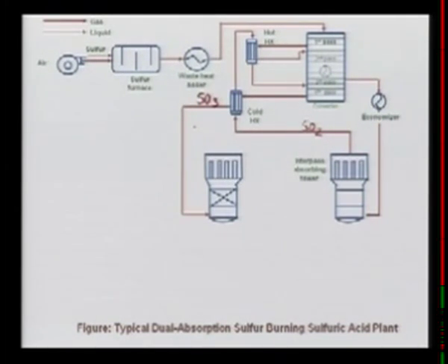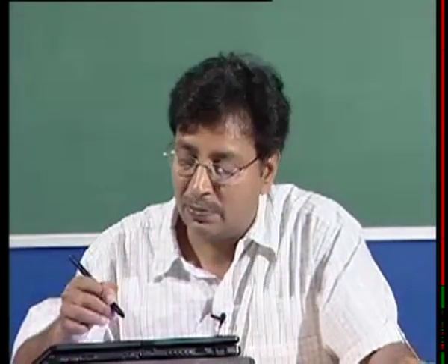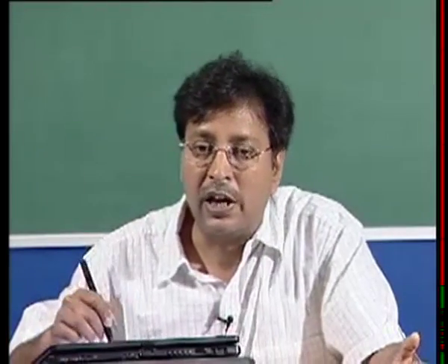And then in the next absorbing tower, whatever SO3 is now converted goes into the final absorbing tower. And you will see here the stack is very, I'll use that word, very little. You can see a little SO2. A good job done, because I could convert the remaining SO2 back to SO3 and use that SO3 in absorbing and making sulfuric acid. So not only did I enhance the value in the system by converting more and more of SO2 to SO3, once SO2 is converted to SO3, the emissions will reduce significantly.